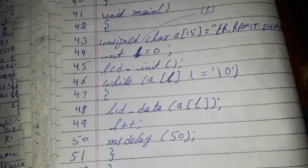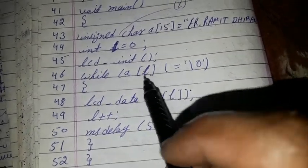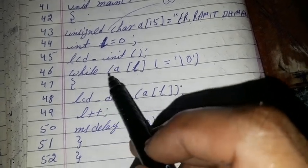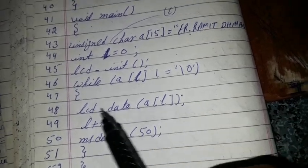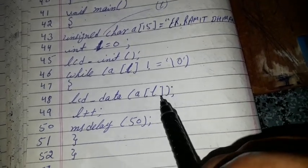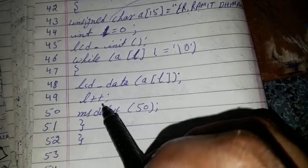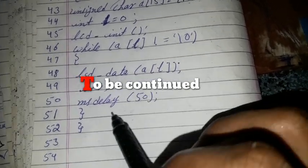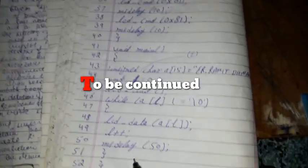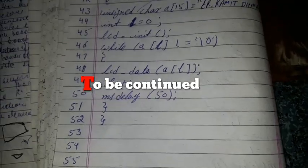Here we initialize an integer, small l equal to 0. l is for creating the while loop. We have the while loop running while the value is not equal to 0. The LCD displays the data from l, from position 0. Here we use l++ with a millisecond delay, so it produces the characters back to back after some delays, and the program repeats again and again. So here is the program, and in our next section we provide the hardware and load the program into this microcontroller.